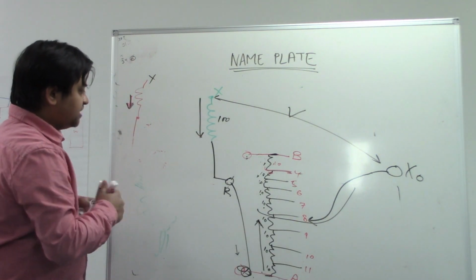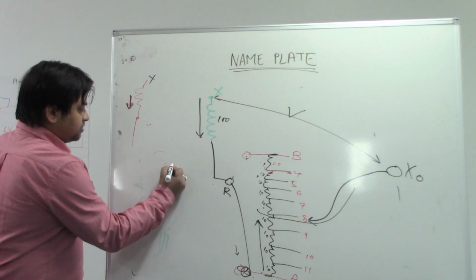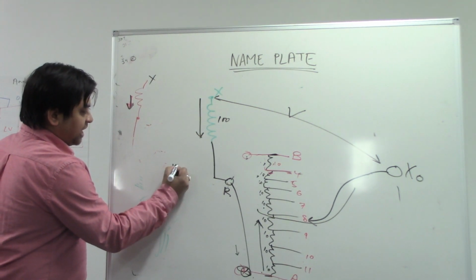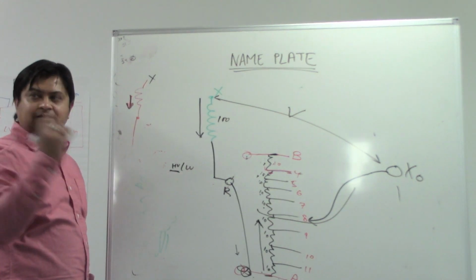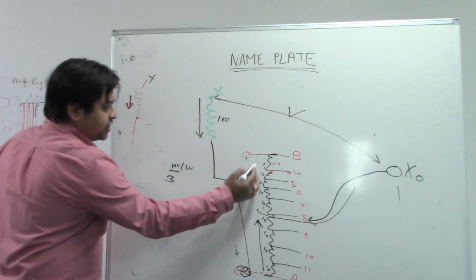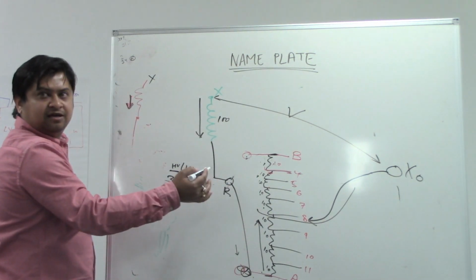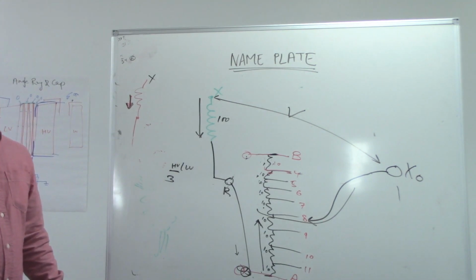Because in this case, when you are checking your ratio, you are checking your high voltage to low voltage ratio, right? So your high voltage you are keeping at number 3, at constant voltage. Then you are changing your ratios like this. So as soon as you are adding up, your ratios will go down.